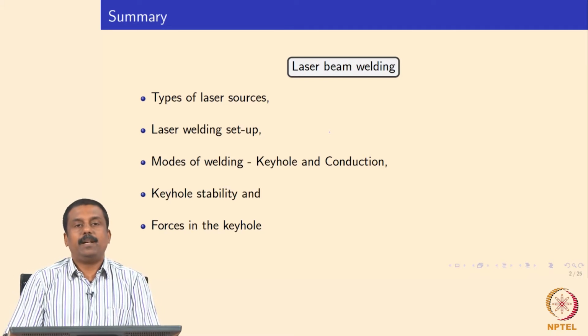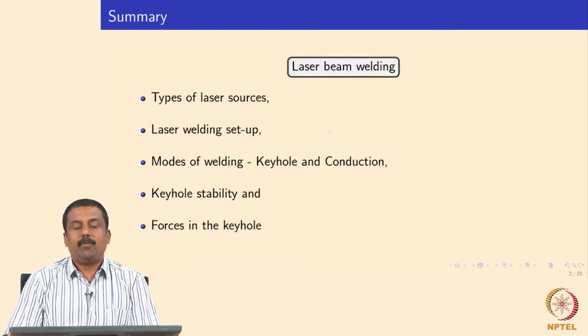So the modes of welding. What is keyhole welding? What is conduction mode welding? What is the importance of keyhole and the reasons why we should have a stable keyhole in order to have a good aesthetic weld as well as a spatter free weld? And we looked at the various forces that are affecting the keyhole stability.